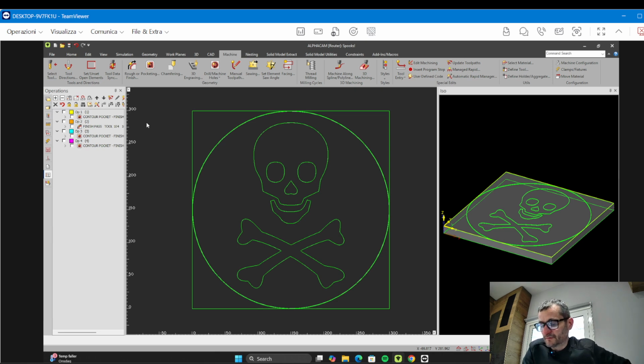And so with the 5 and 16 tool, for example, you do everything more or less. If you have a big area, for example, you use a 50, 60 millimeter tool because you have to clean a big area. In this case, maybe you have to make 3 passes. There is no big rule, no correct or incorrect way in this kind of thing. I think after you test on the machine, you have your answer.